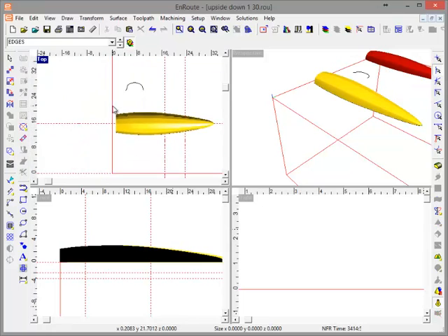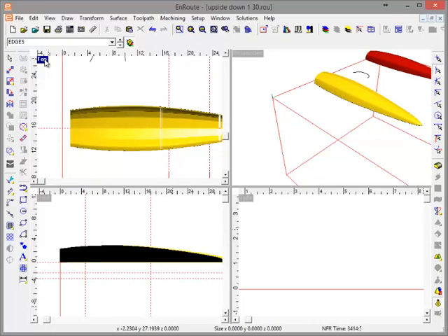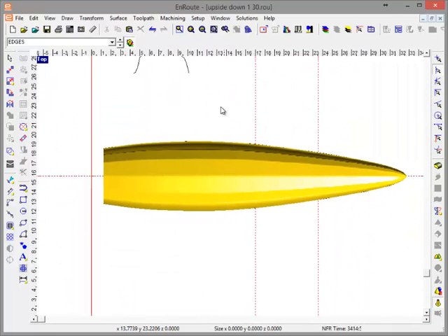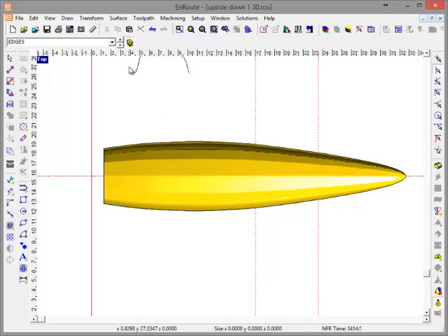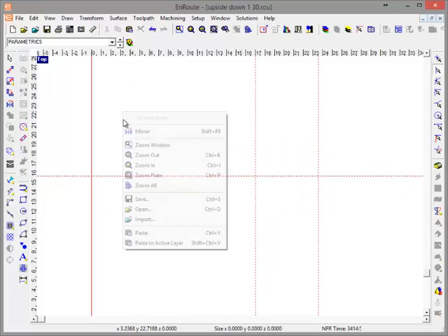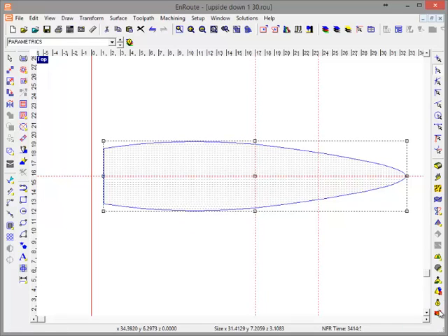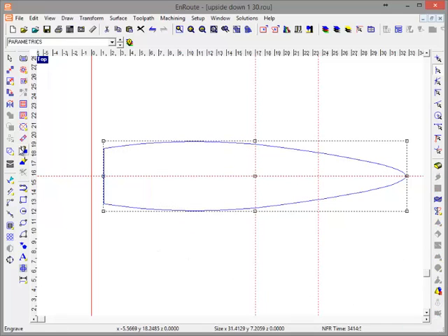All right, now if I want to break this in part, then I have to come here, and again, it might be helpful just to have the same contour. So I'm going to say Control C, paste this to the active layer, and get rid of the relief. Now I'm going to come to the welding toolbar button and go to the cut by line tool.